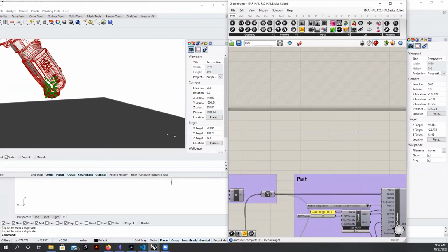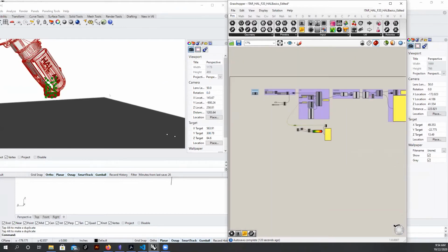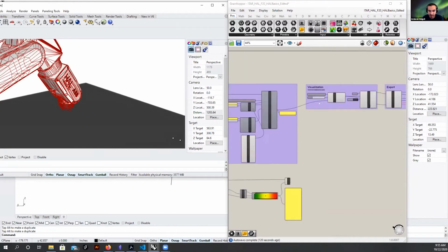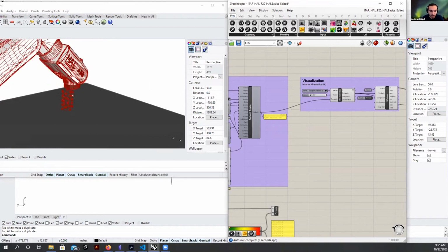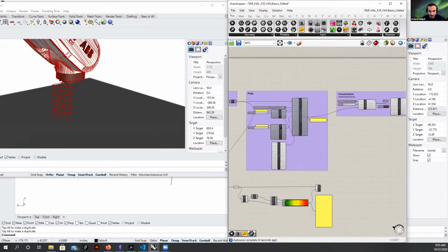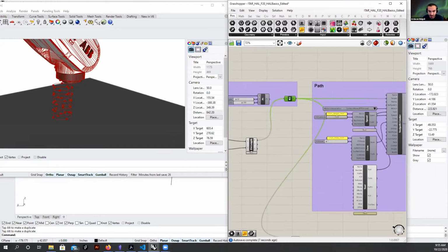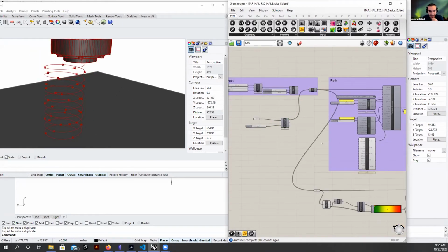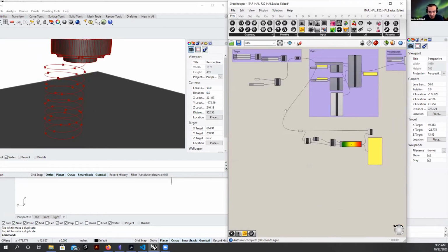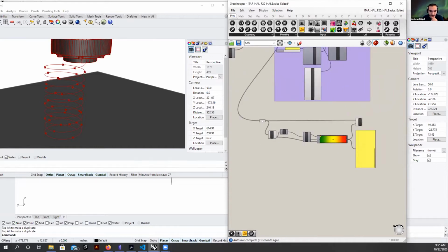Okay, no problem. So basically, first, can you move your robot up? Go to the slider that does the simulation, the visualization, and make it 0. Okay, good. And then hide all the points before it. Whatever you have before. Yeah, that divide length, just hide that one. Hide is the one with the blindfold. Okay, good. And now you have those points at the bottom, so hide that point component also. Oh, okay, I see that.